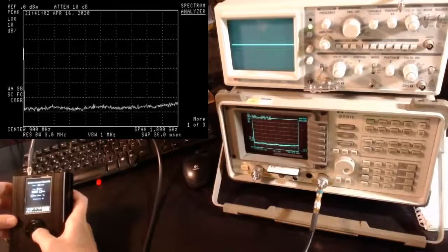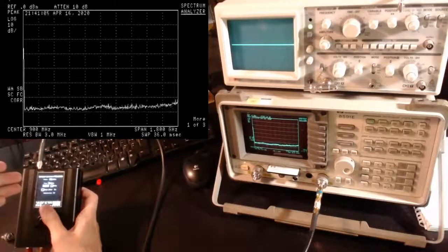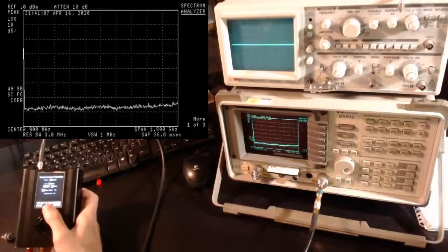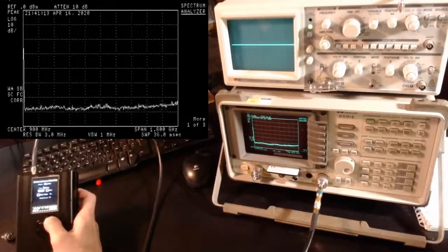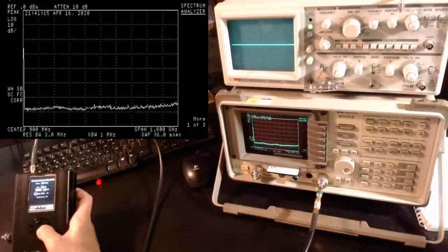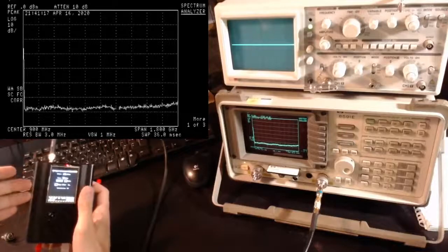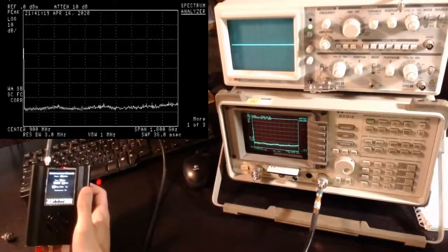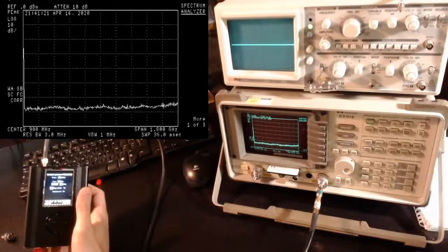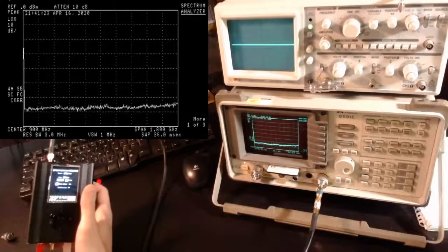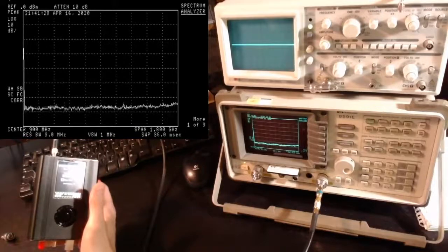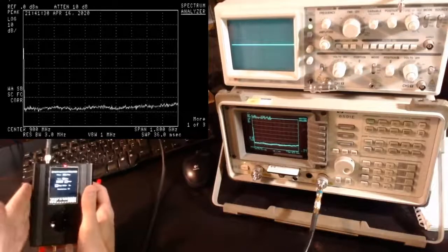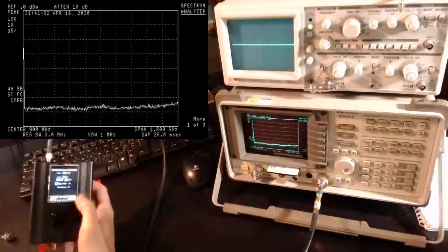So for example, if I modulate a 0 hertz signal, so no signal at all, I will just get a sine wave. So this is going to be my basic setup, just a sine wave at arbitrary frequencies. And essentially this part of the video will be very similar to my previous video titled the HackRF as a signal generator, except that instead of using a very basic GNU Radio Companion sketch as I did last time, I have this interface, this manual interface, which is quite handy.